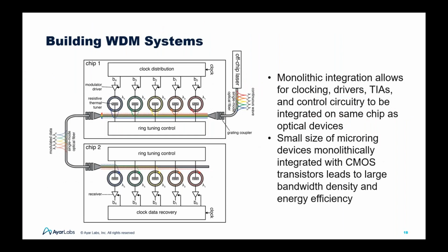This is basically a larger ecosystem, a system of the optical link. Again, we're going to have an off-chip laser. There are two advantages to putting the laser off-site. First of all, the laser is very sensitive to temperature. You can have it as far as possible from the hot electronics that you have, which increases the reliability and lifetime of the laser. And number two, generating laser in CMOS is usually impossible because of the nature of the CMOS.